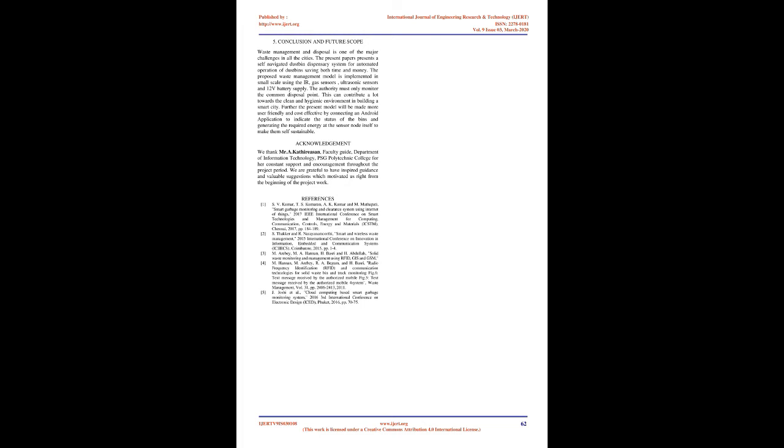L293D consists of two H-bridges. The H-bridge is the simplest circuit for controlling a low current rated motor. We will refer to the motor driver IC as L293D only. L293D has 16 pins.